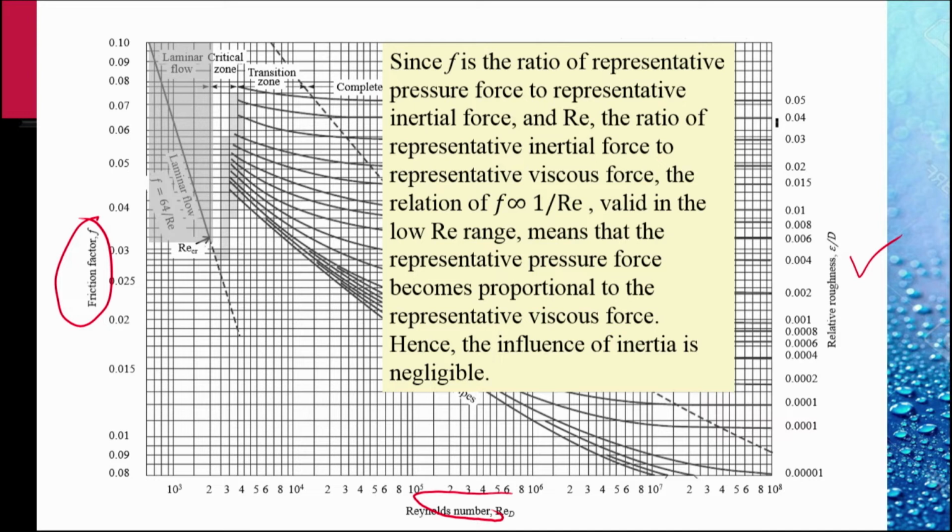So, for modeling this laminar flow, we could neglect the inertia force completely. The result is obtained by balancing the pressure force with viscous force alone.